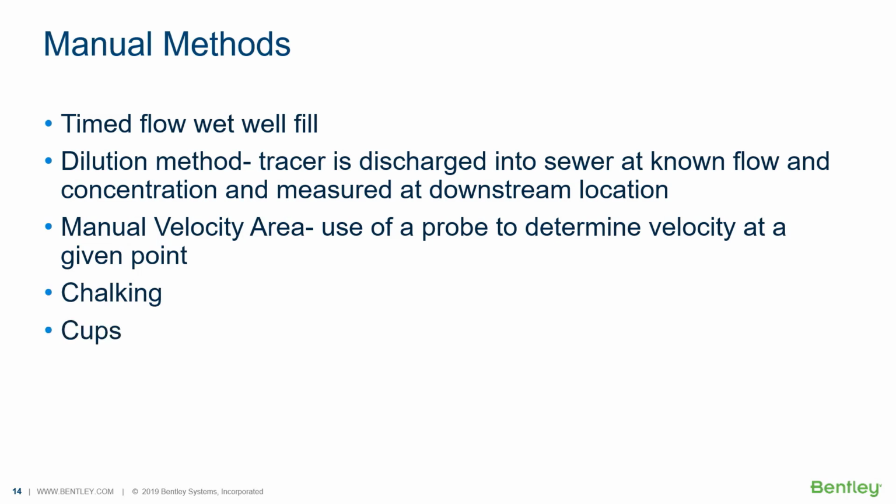Then there's things to figure out. Are manholes flooding? There are some techniques where you just basically put a chalk mark inside the manhole before the rain, and you go back afterwards and see how much that chalk was erased. And that'll tell you how far the water backed up into the manhole. Or you could hang a series of cups from the side, and see which cups are full after a rainfall event. You get an idea of which manholes are getting surcharged. You don't have to be out there in the middle of the biggest storm to try to catch this sort of thing. So those are just some simple things that you can do with a minimum of technology.